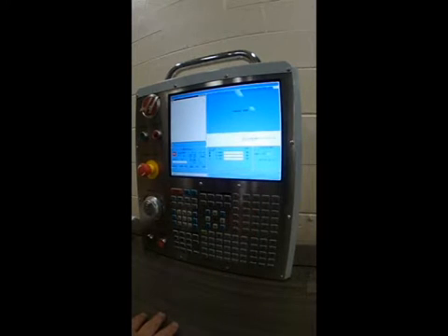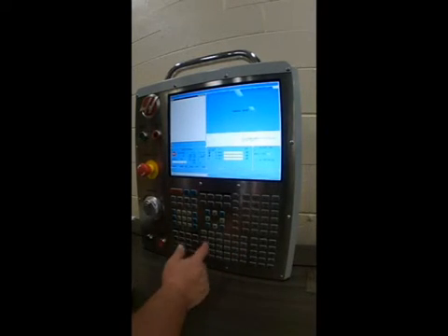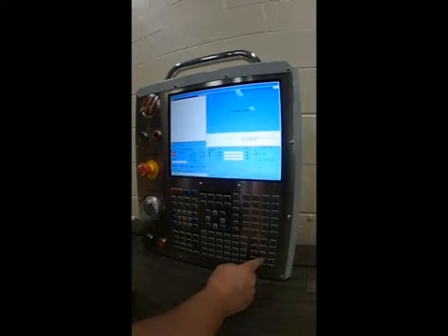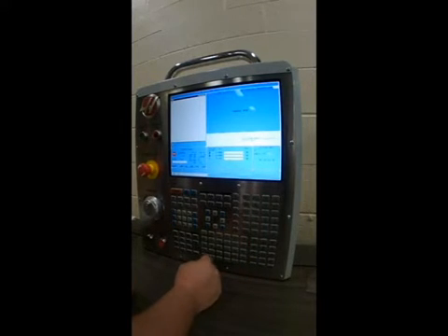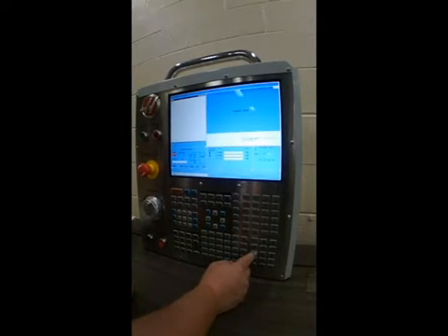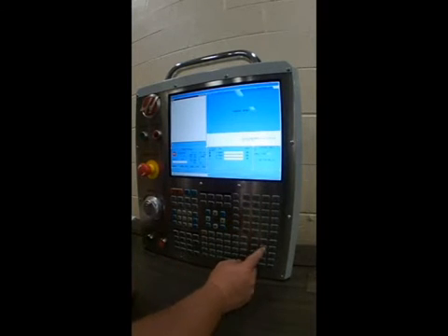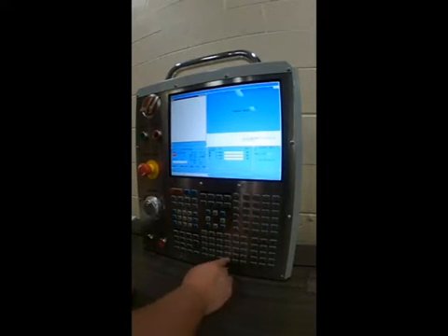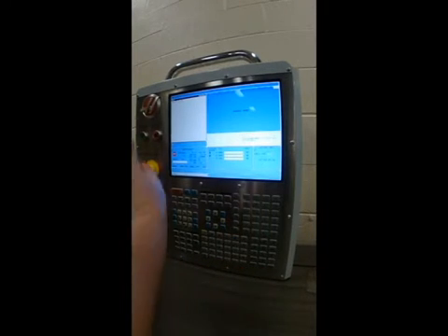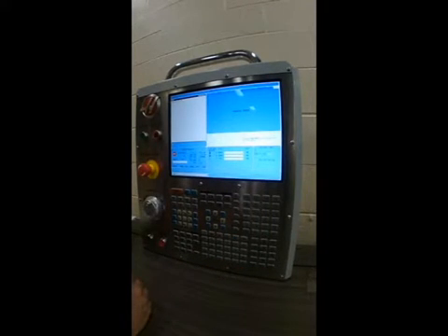And at that point, the machinist really became a programmer rather than an operator. So the machinist would formulate instructions to put into the machine. Let's say G01, Z10 with a feed rate of 5. Alright, and so that simple line of code is enough to cause the machine to operate.